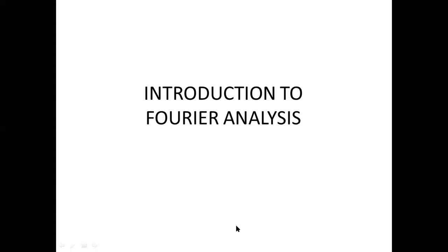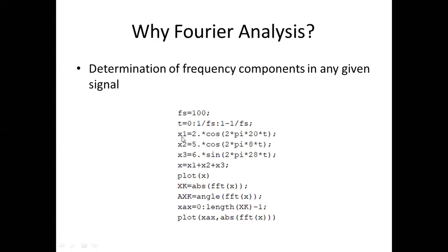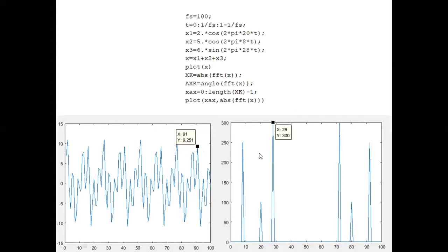Yesterday we had started this, right? What is the use of Fourier analysis? Yesterday we discussed this. If you happen to have a system with different frequencies and you don't know which frequencies are present in that system and what is the contribution amount of power in each, you simply take the Fourier transform and you will automatically come to know. Whenever I take a Fourier transform, you will see a signal and its replica on the second half also. Neglect it; we will address that issue later. So one of the applications was predicting the different frequency components and their contribution.